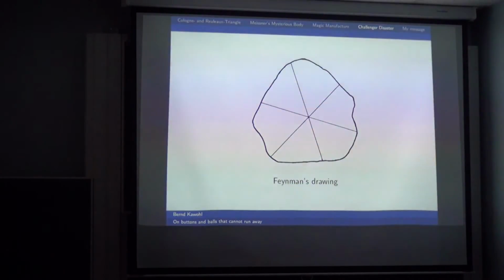If you deviate from a perfect circle by this much, the O-ring cannot accommodate the difference. There is a gap. Something will come through. And you do not see with the naked eye that it is out of shape. And you cannot measure it because there are these sets of constant width. Don't you know? And they did not know.